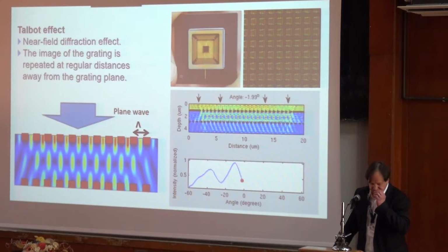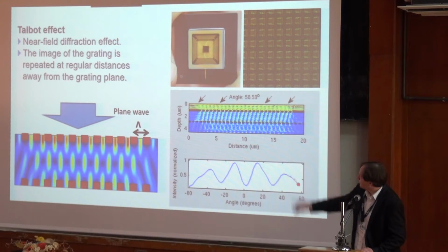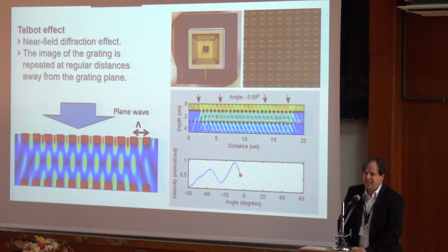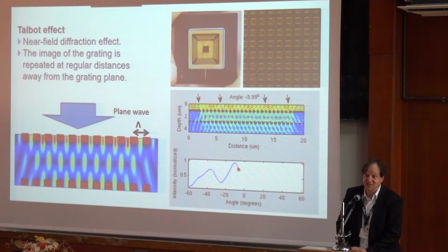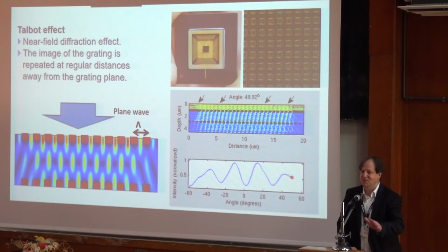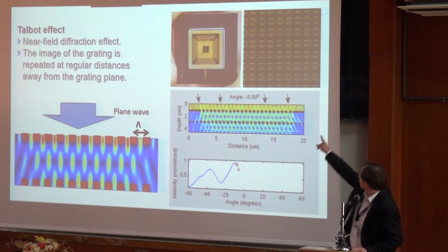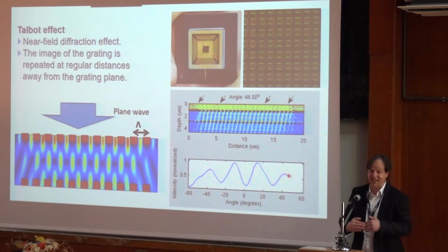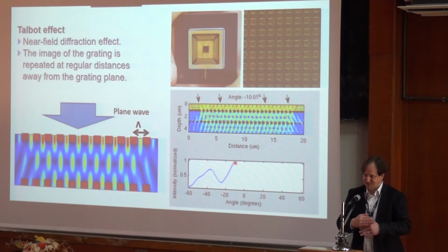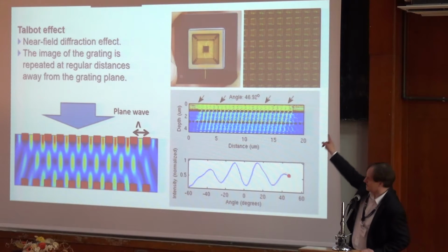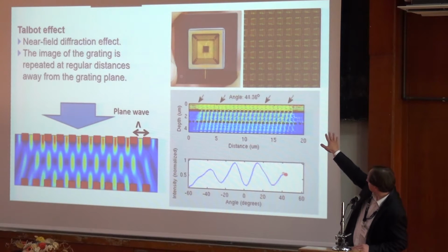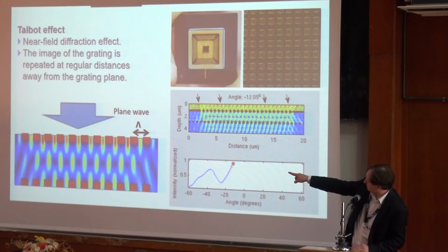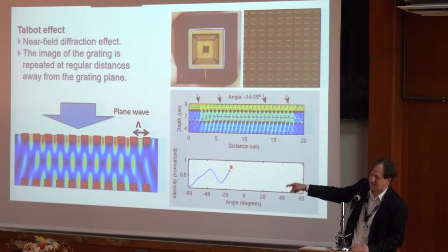And what we can also do is, like in radio, use something like a Talbot effect to create angular sensitivity. So beamforming can be done at a receiver as well, without any hardware, without any electronics, without any energy. What we've done is a metal grid. It's a metal layer on top of the CMOS structure, and we created something like a blind system with different structures of metals, and then you get light through, and the Talbot effect says that you repeat the incoming pattern regularly.